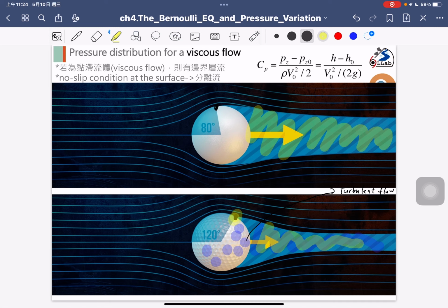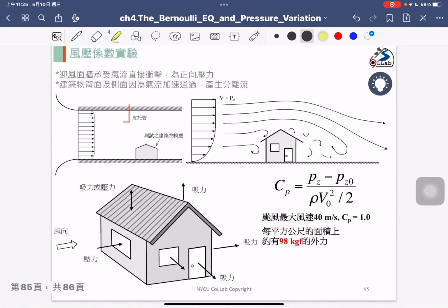from happening, and we will reduce the wake flow effect. If we can reduce the wake flow region, the drag force also can be decreased. Okay, so that's the idea when we describe the pressure field based on the CP coefficients. And this is another case.